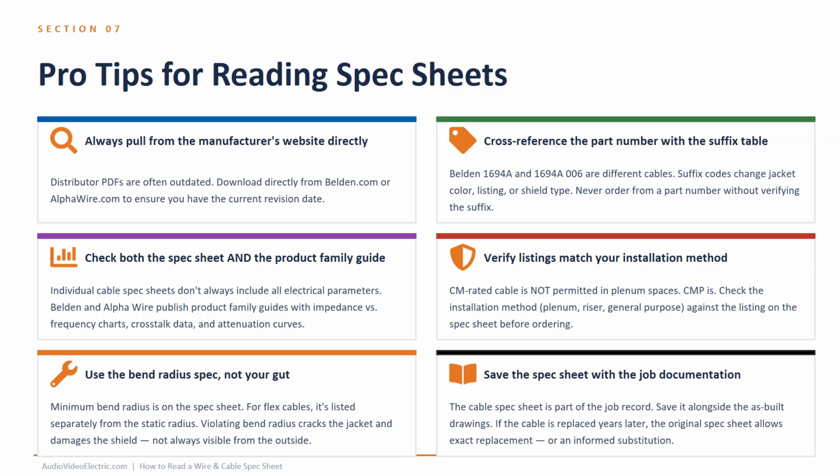Verify that listings match your installation method, plenum, riser, or general purpose. Use the bend radius specified, not just your gut. Finally, save the spec sheet with your job documentation for accurate replacements or substitutions in the future.